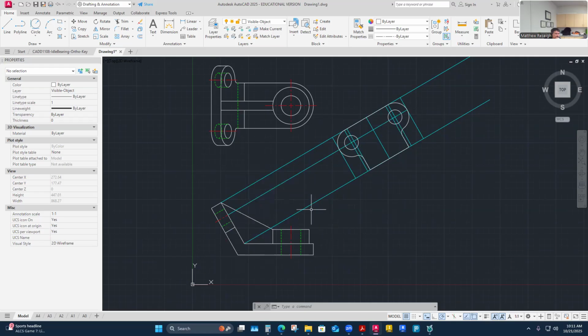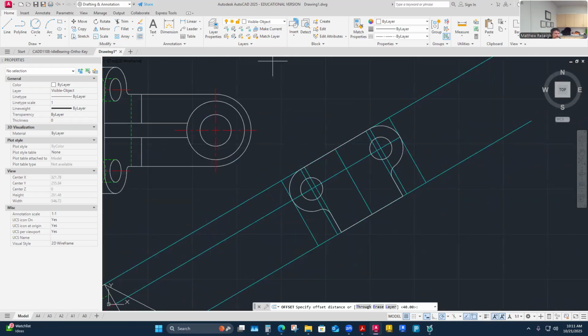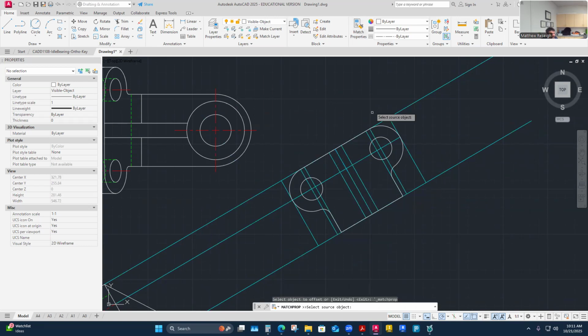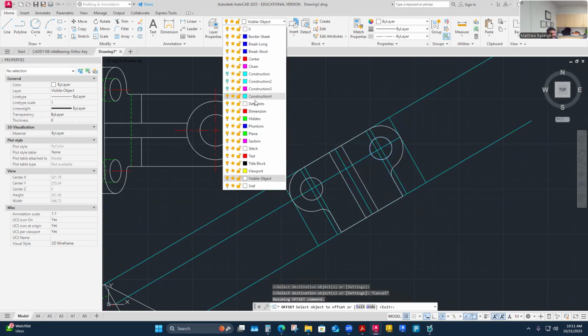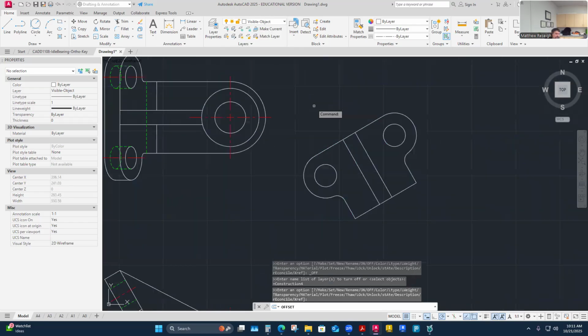So my view is definitely looking down. I'm in orthographic alignment, but I'm going to do an offset of 8 again because the gusset's 16. I'll just use my center line for my gusset here, and then I'll change those properties so they look like a gusset. And then I'll toggle off my construction layer here. Yeah, that looks correct, huh?